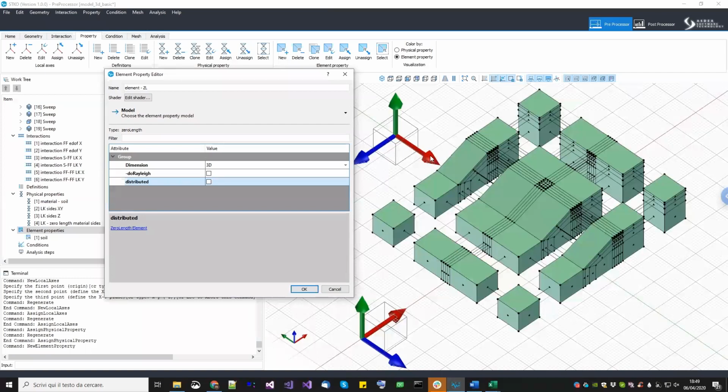So if you want to do this kind of boundary by hand, you need to provide a dashpot connecting every node of the master slave faces. And for every zero length, you need to provide an equivalent area. So you need to do the lumping by hand. This means basically that every node-to-node link potentially has a different value. And this one is very inconvenient.